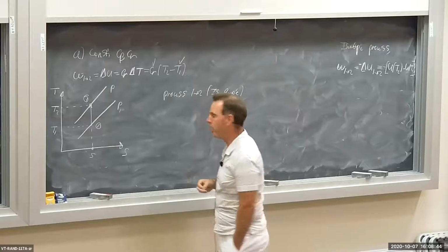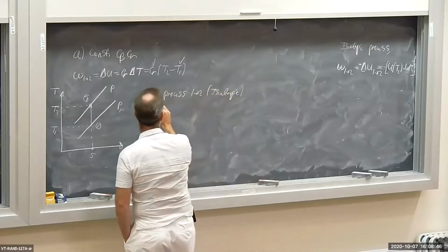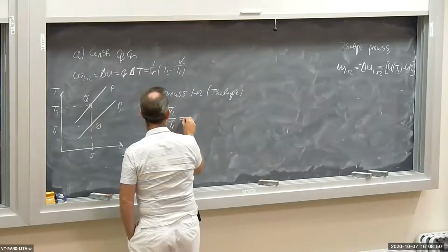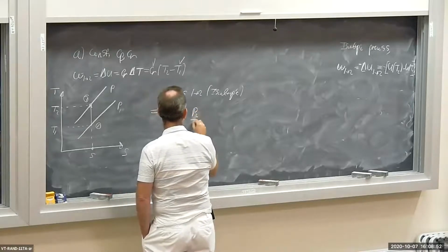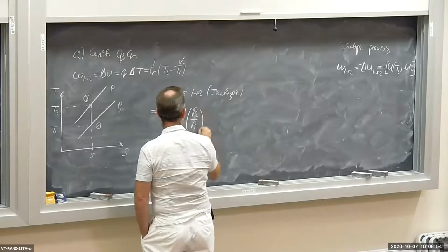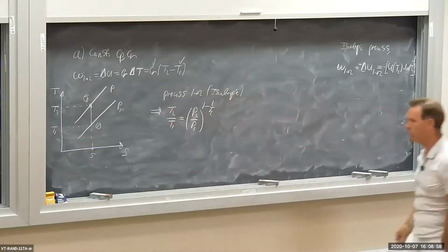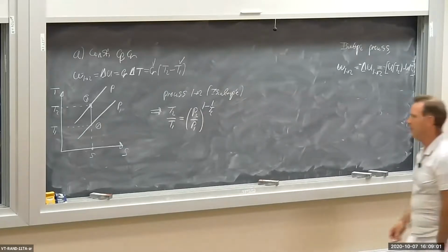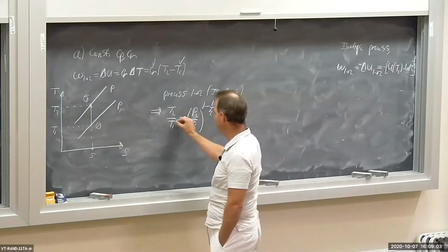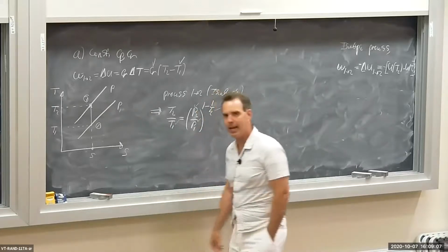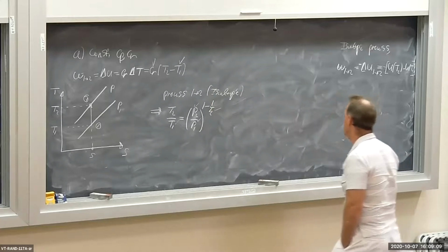That means I can use an isentropic property relationship. T2 over T1 is equal to (P2 over P1) to the power of 1 minus 1 over K. So there's our isentropic property relationship. Note, I know T1, I know the pressures, initial and final, and I'm given K. I have everything in this equation. I can immediately solve for T2.